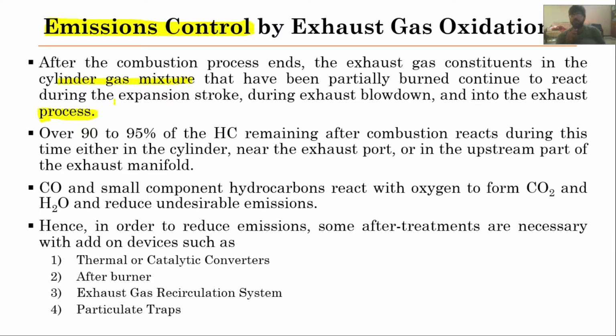Therefore over 90 to 95% of the hydrocarbon emissions, those hydrocarbons which haven't combusted yet during the combustion process, usually react during this phenomenon, either during the expansion stroke, or during the exhaust stroke, or in the exhaust manifold as well.